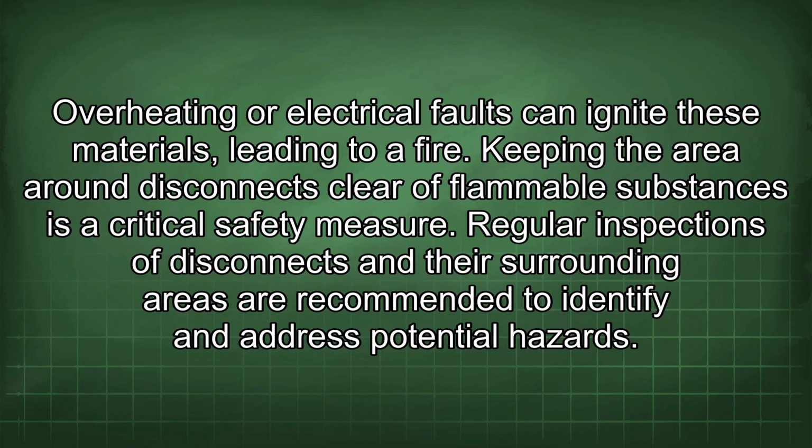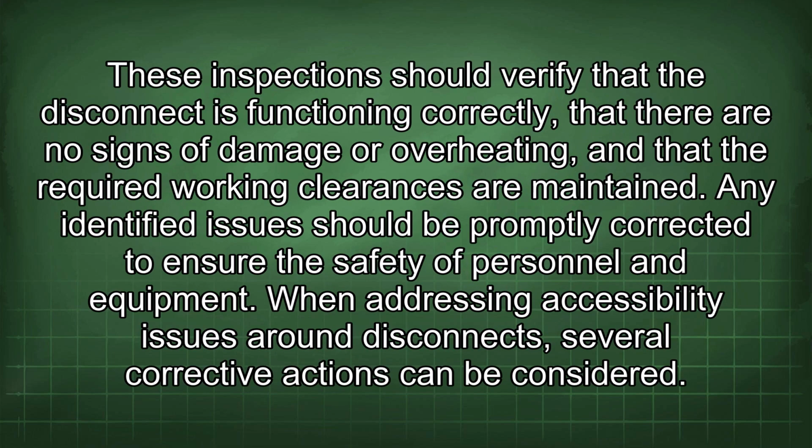Regular inspections of disconnects and their surrounding areas are recommended to identify and address potential hazards. These inspections should verify that the disconnect is functioning correctly, that there are no signs of damage or overheating, and that the required working clearances are maintained. Any identified issues should be promptly corrected to ensure the safety of personnel and equipment.